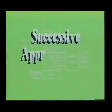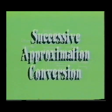Of all the techniques that have been covered to this point, the successive approximation approach has become the technique of choice for the analog to digital converter. This is due to its low cost, moderate resolution, and high speed. The successive approximation converter operates by making several successive trials comparing the analog input voltage with a reference signal generated by an internal digital to analog converter.